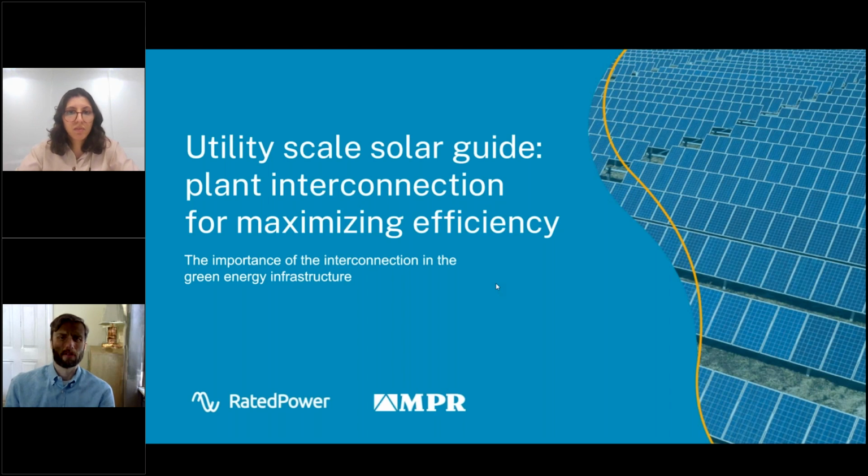That's maybe pretty obvious, but then you start getting into what power factor is required by the grid. At a lot of places in North America, it's 0.95. You have to supply that day or night is becoming the standard. So that can be a little bit tricky if it's solar only. You've got to make sure that the inverters can provide reactive power at night. And then also the power factor changes your apparent power rating for the plant. So those are some of the very high level design considerations or technical parameters that need to be considered.